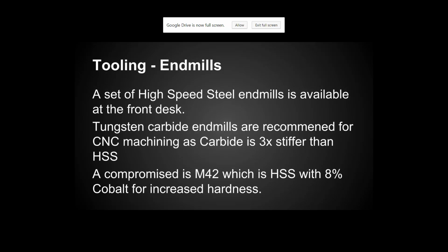Now, there are some tungsten carbide end mills. That's what we hand out in class. Tungsten carbide is about 3 to 4 times stronger than high-speed steel. Downside, it's much more brittle, so you must be sure that your G-code is not going to have an abrupt start. You'll see in 2D there is the, what is it? It's the one that has unabrupt movements for facing. Can't remember the name of the operation exactly.